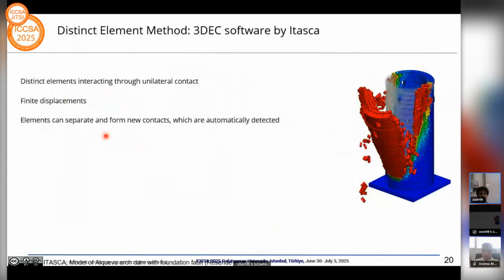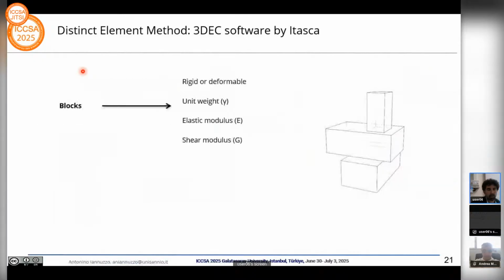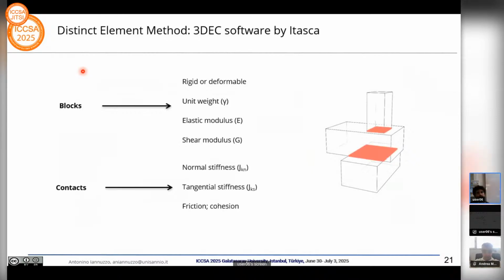The distinct element method can be defined as solved if these three assumptions apply. Essentially, you can model blocks as rigid or deformable. You can also provide internal interfaces where you can provide a non-negligible tensile capacity for the contact, which is mainly ruled by normal and tangential stiffness.